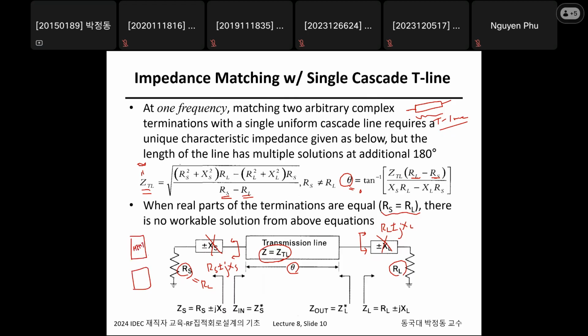right? Let's say this matching network for the power matching line, the required impedance is G opt, right? And this is also G opt. But unfortunately, if G opt is much, much smaller than G naught, GL, which is typically 50 ohm, this is getting worse, right?